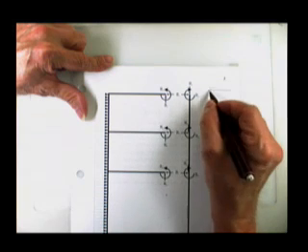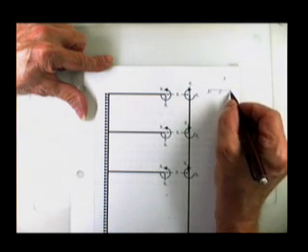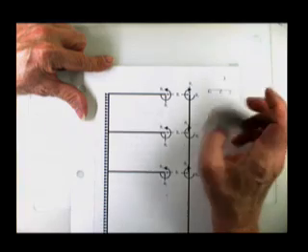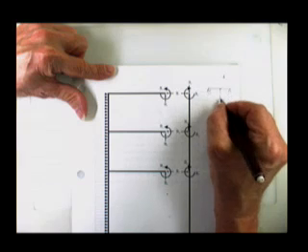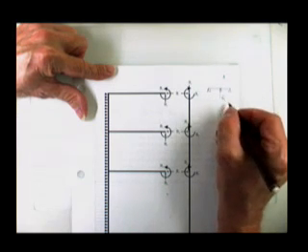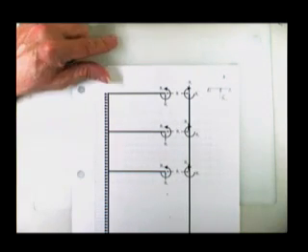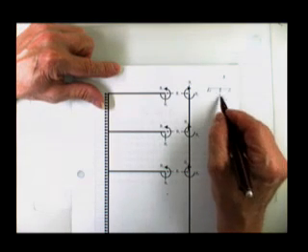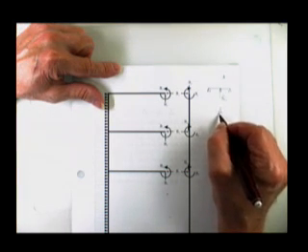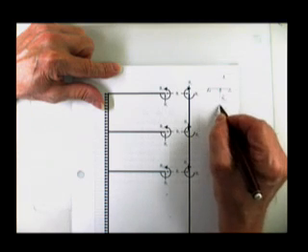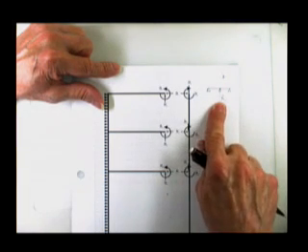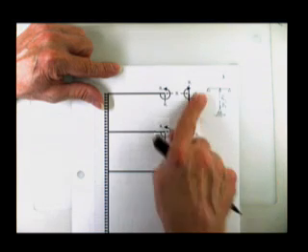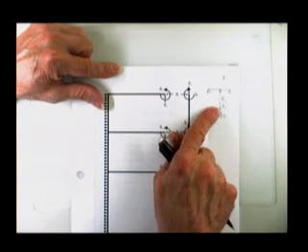You're used to seeing a beam and a reaction and a reaction, and when you took loose this reaction, you replaced it with a force. Maybe you called it R1. But in the real world, underneath R1 was a pin or a roller, and R1 was pushing down on the ground. Even when you really never saw it up till now, there was a matching force that had his feet pushing against something.